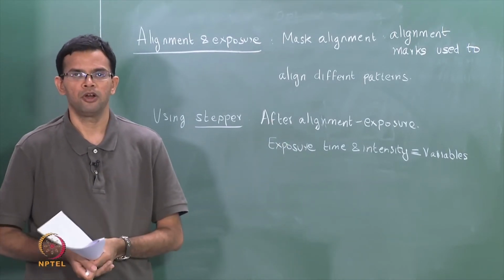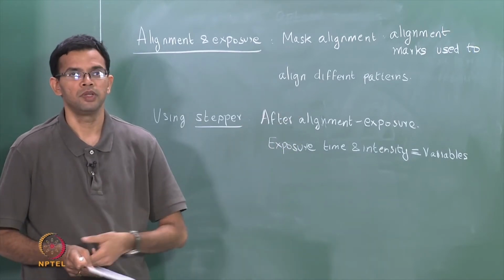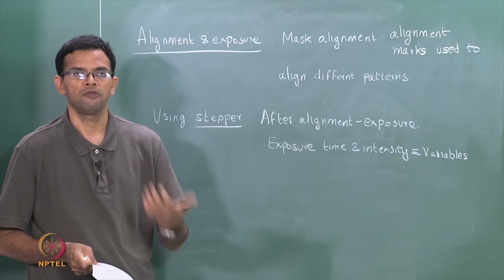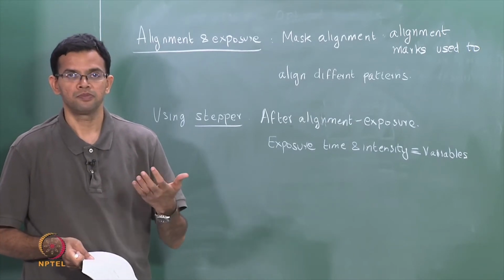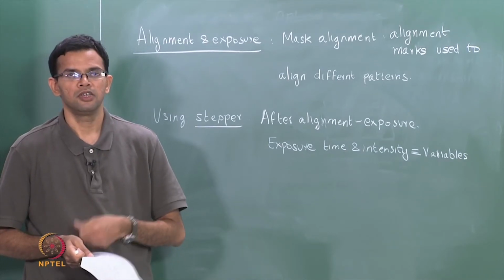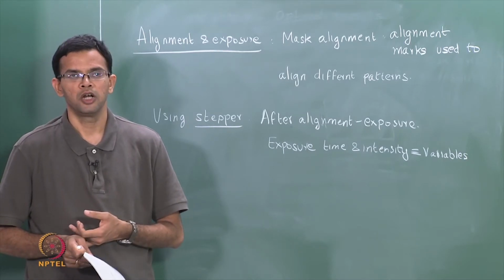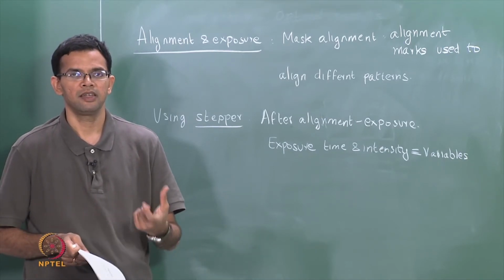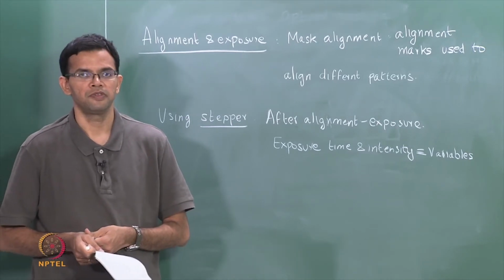After the exposure process is done, the whole thing can take place in less than a few minutes, which is why lithography is such a fast process. You can go on making multiple patterns or multiple copies of your mask. So even though the original hard mask can take hours to make, once that is done, the pattern can be quickly and effectively transferred to different wafers.